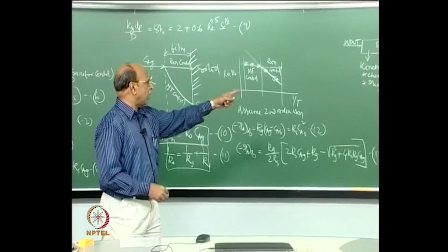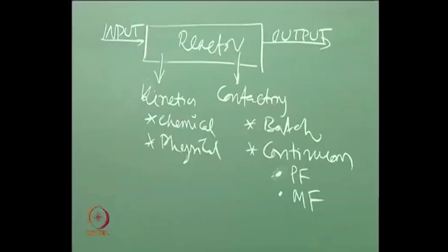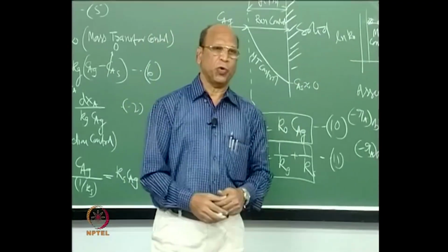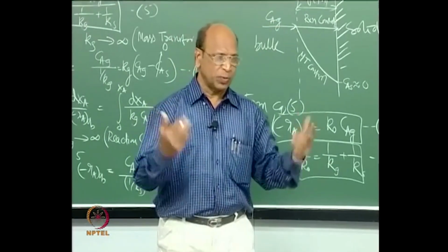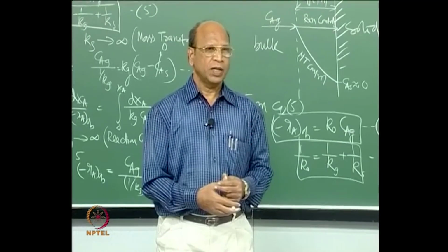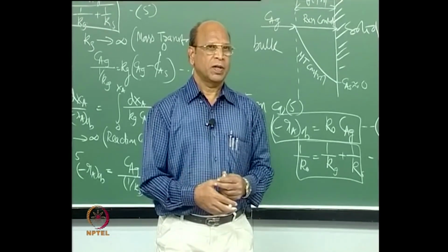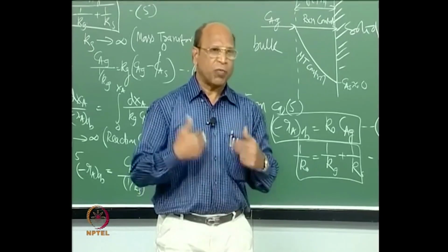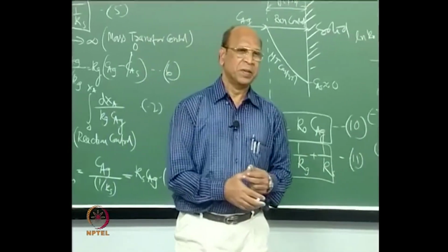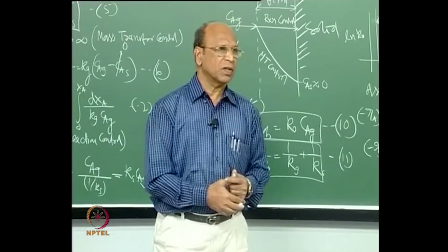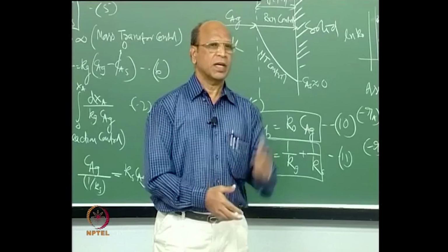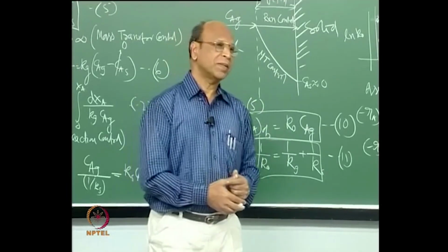Once you have chosen between batch and continuous, in continuous you have again two possibilities, plug flow and mixed flow. So, when do you choose plug flow and when do you choose mixed flow? Abhinav, do you remember? For higher conversion or the same amount of volume. See, all of us always want higher conversion. Yeah, I have given some thumb rules again. Prabhudev, okay. Excellent, good. Why?